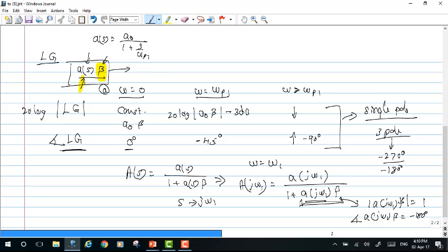So now, how would I put them as magnitude and phase? These two pieces of information could be clubbed as something like A of j omega 1 times beta times e to the power of the phase angle, which we normally write like this. So this becomes a quantity whose magnitude is equal to 1 and phase angle is 180 degrees, or in short, this entire term would become a negative term, and that is what we generally mean mathematically, correct?